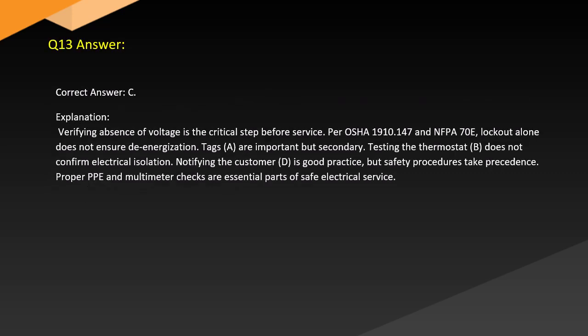Answer. Correct answer C. Explanation. Verifying absence of voltage is the critical step before service. Per OSHA 1910.147 and NFPA 70E, lockout alone does not ensure de-energization. Tags (A) are important but secondary.